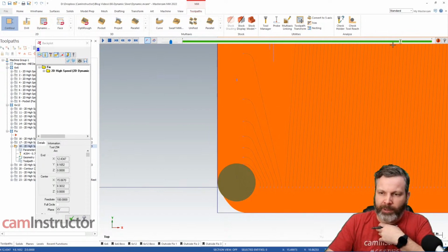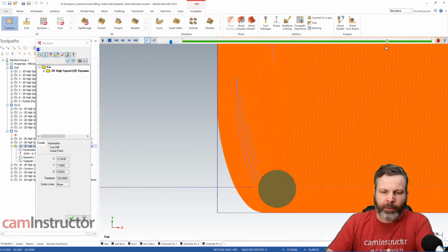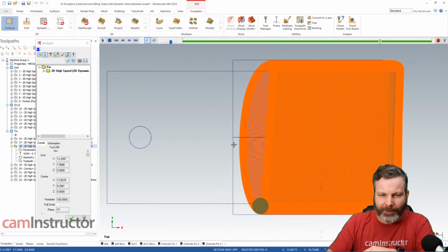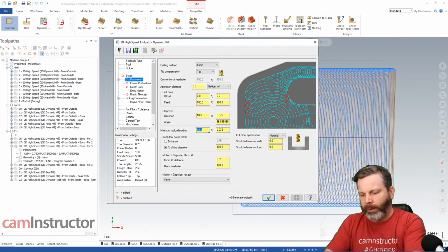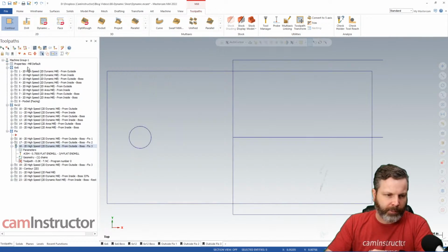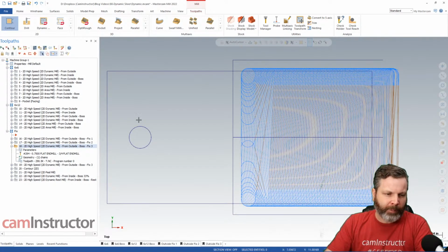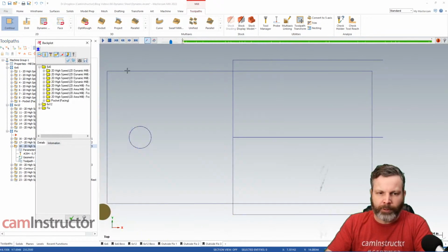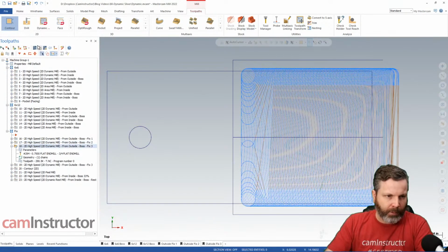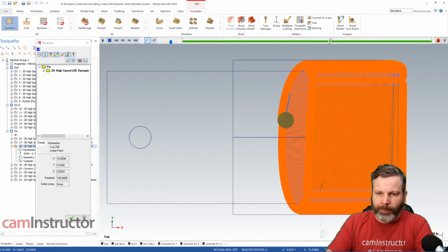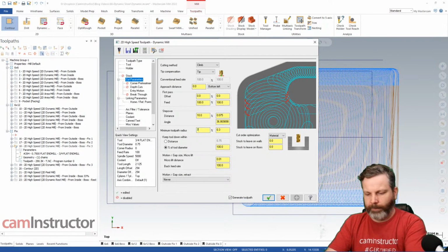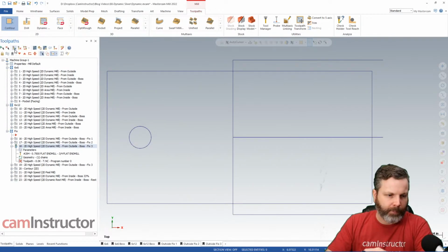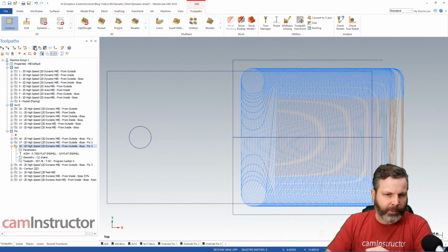And we don't need to be nibbling away at these corners. There's no need for a sharp corner if we're going to be machining all this stock away anyway. So what we could do here is fill the shape of the corner. We could limit the toolpath here as well. We could say, I don't want to be getting down that sharp, so maybe 400. That'll keep it a little bit flatter, but even still, that's probably getting too sharp. It's too much work in the corners for a part like this. And then also we need to keep in mind, if we were to do a path like this, that's not exaggerated enough. That's probably still not exaggerated enough.